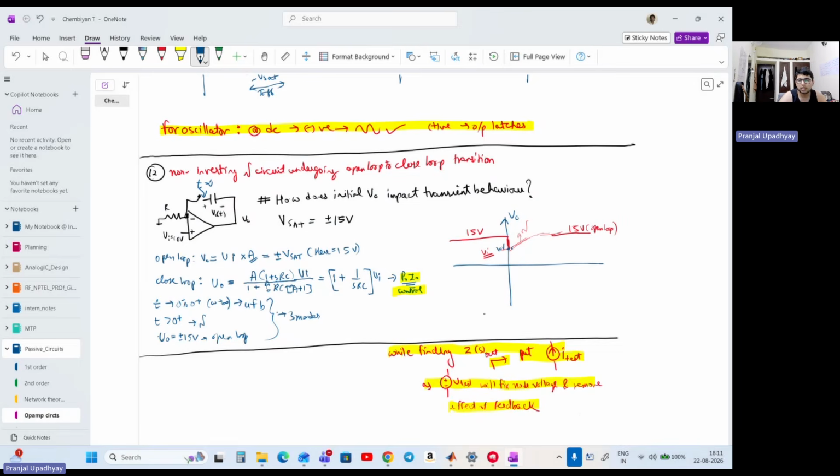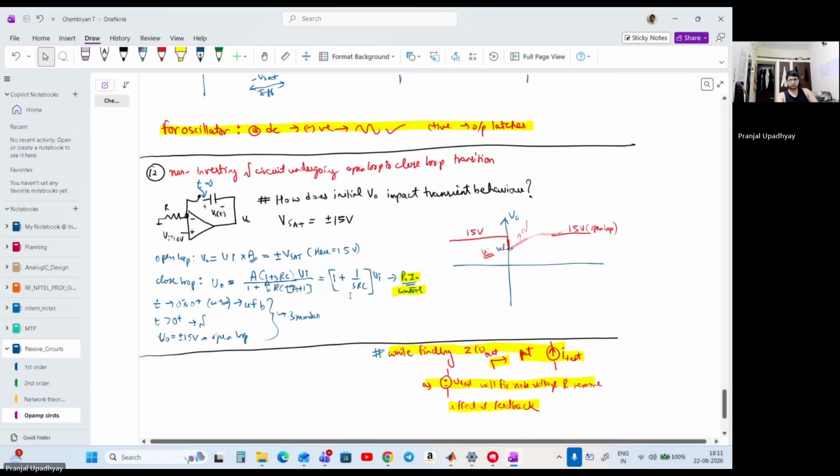The last note that I've written here is that when finding the output impedance, put a current source to determine the output voltage, because a voltage source test can change the node voltage and remove the effect of feedback. This is something we can understand only in practice. It's a note I've written for myself for the future, but it will be more obvious when we try to solve questions posing such a diagram.